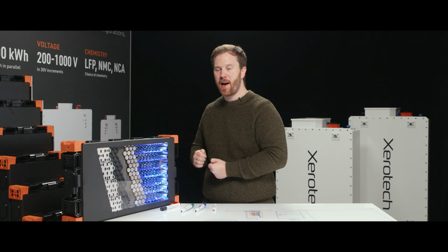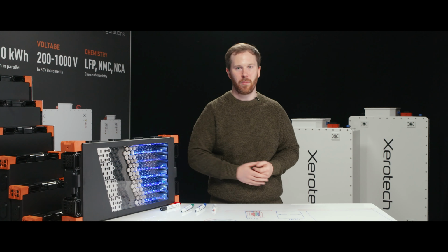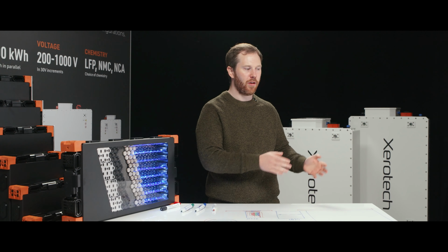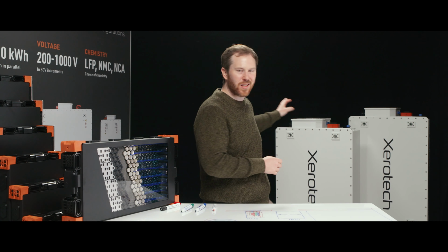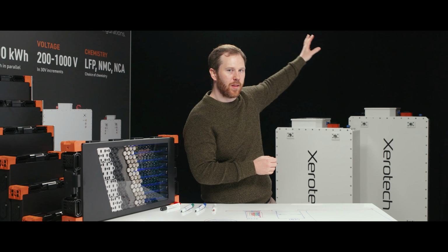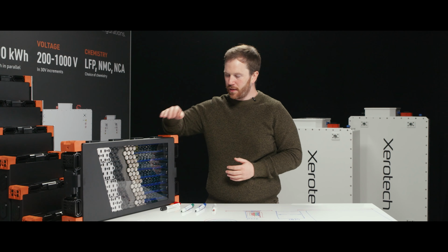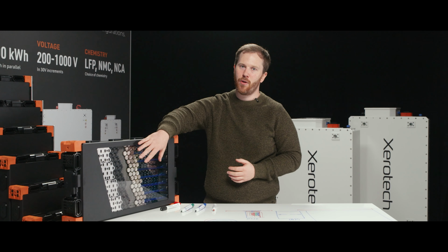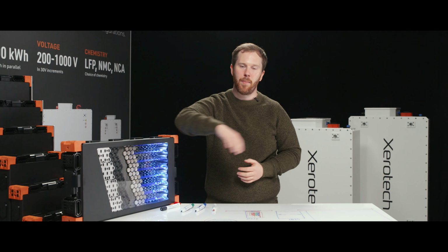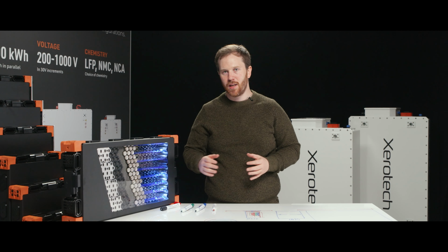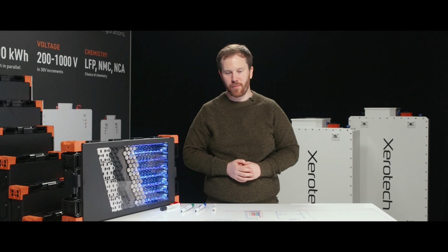Important to point out that very few packs have thermal management in them. What they have is heat exchangers. Heat exchangers get the heat in and out of the pack. A thermal management system like a heat pump, an electric coolant heater, a radiator is all outside of the white box, somewhere else in the system. So that's separate to the battery packs, as are the pumps. So this gives you a super highway in and out of the pack or in and out of the module, but it's up to the end users typically to get it off their vehicles or out of their systems.